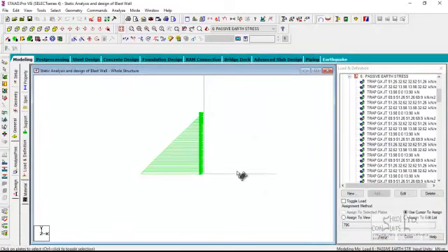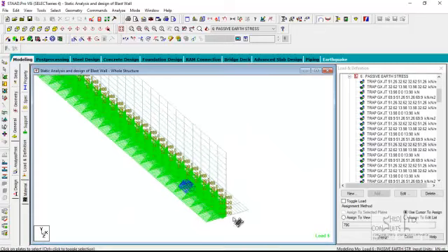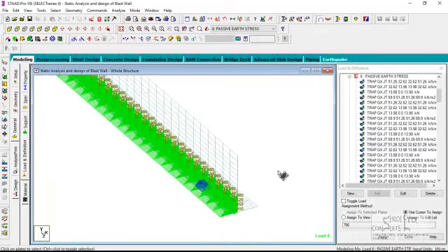If we look carefully, we'll see that the passive earth stress varies from 0 at the soil depth of 0 to 69.9 at the soil depth of 1.5. So the founding depth of the foundation is 1.5. 1.5 is as a result of the DEP requirement that the depth of a blast resistant structure will be such as to prevent a continuous build-up of pressure, an increase in dynamic air pressure in the event of an explosion. So in the event of an explosion, there's a potential for an increase in dynamic pressure if the founding depth of the foundation is not suitable.